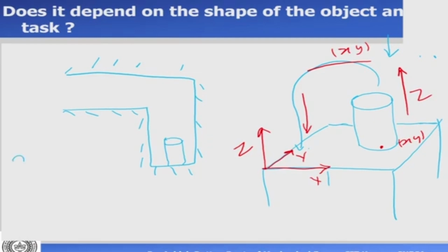So if a robot is here, let's say there is a robotic system here, it has many links. The robot is going like this, like this, and like this, trying to catch it. The moment it has entered this hollow section, some of the degrees of freedom of this joint will be lost. Why? Because it can't move up and down, it's constrained now.